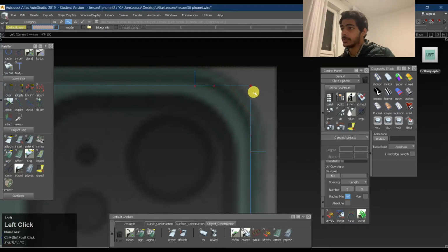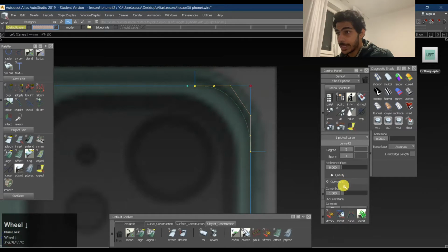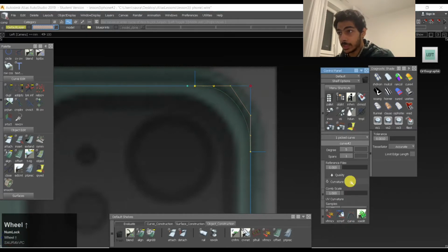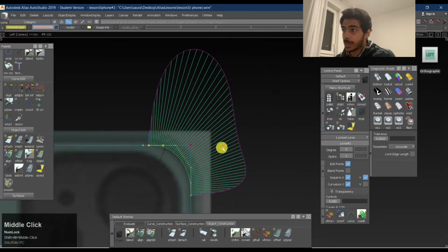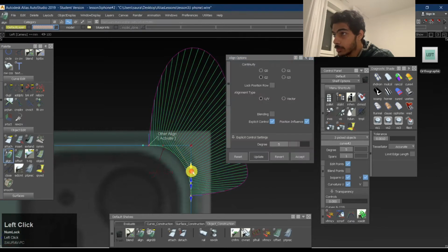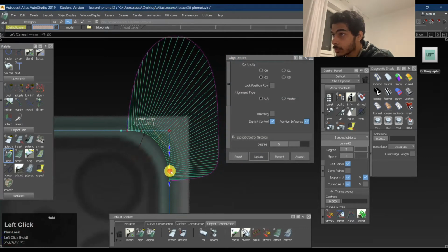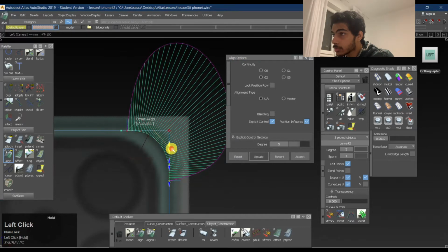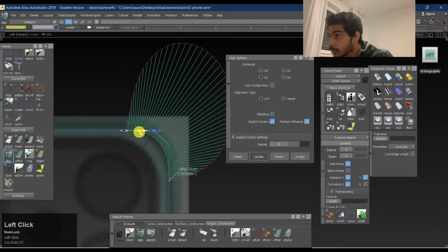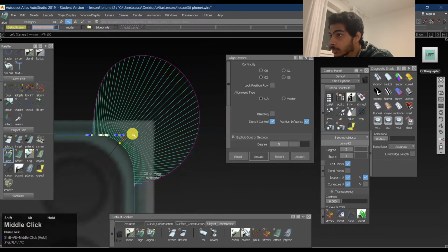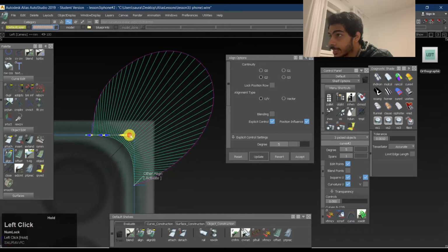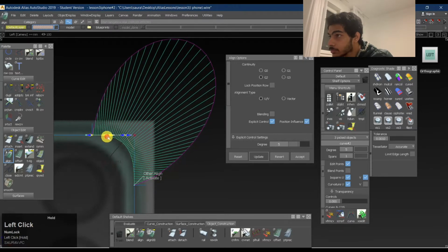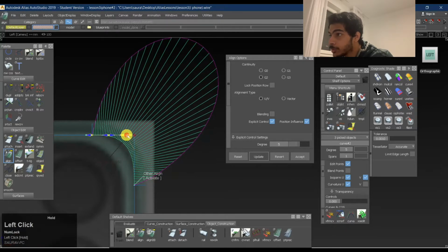I can also see the curvature comb for this, which is over here, and I go into the curvature tool which I showed you in the previous lessons, and I'll check the curvature hue. And I'm not happy with this curvature comb. I'll try to play around with this as well. If you see, I'm trying to play around with it a bit so that I can get my desired values. Somewhat like this, but obviously it's bulging a lot, right? It's bulging a lot. Maybe we can try to push it in a bit.